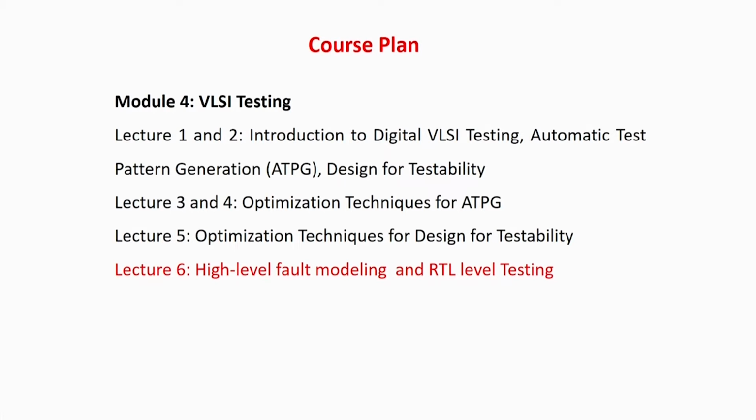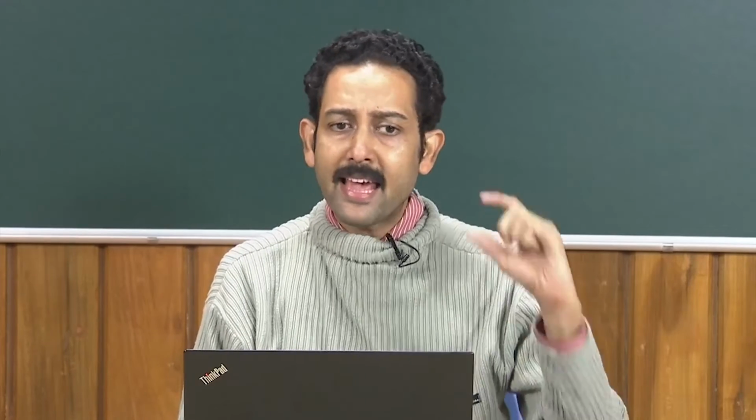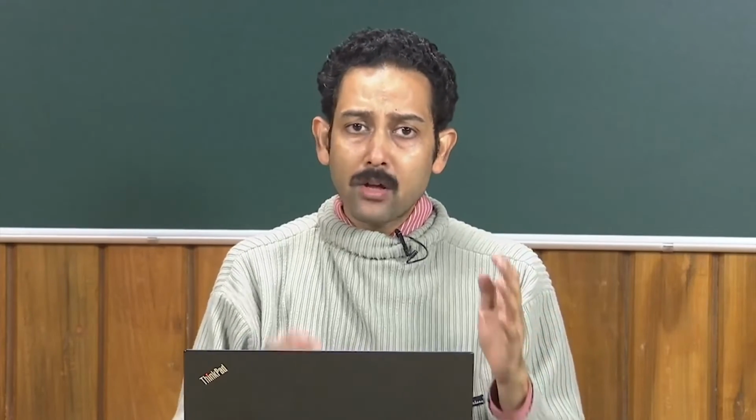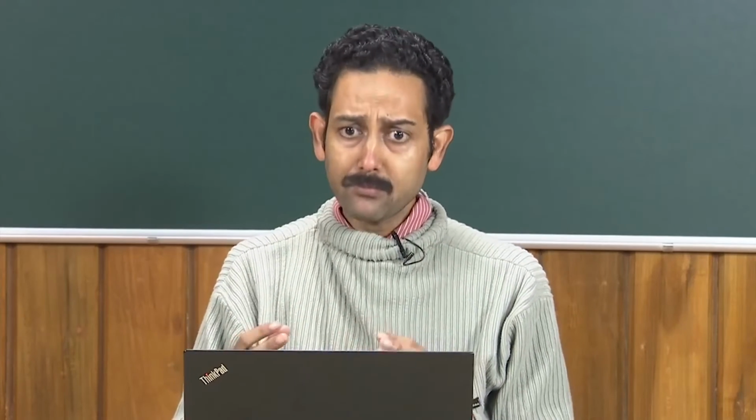So, today's lecture will concentrate on the directions people are thinking about, on how we have to move away from gate level modeling and analysis to some level of abstraction like register transfer level. The motivation: before these NOCs and SOCs, we were looking mainly at the gate level. Now, why at the gate level? Because the gate level has a good correlation with the transistor level and the basic device level. And when you talk about structure, we do not think about the functionality of the circuit.